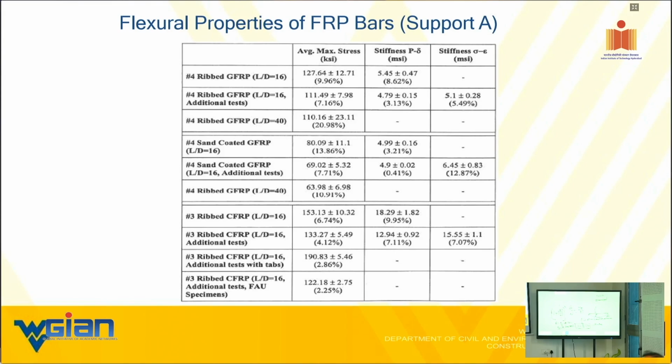People are using thermoplastic resins also. We don't use thermoplastics for main rebars. Yes, we do use thermoplastic for stirrups, because that's easy to make and bend, but not for the main rebar. Its molding becomes a bigger problem with thermoplastics.